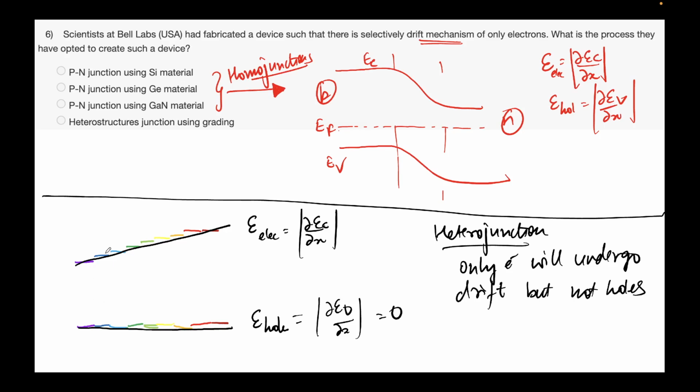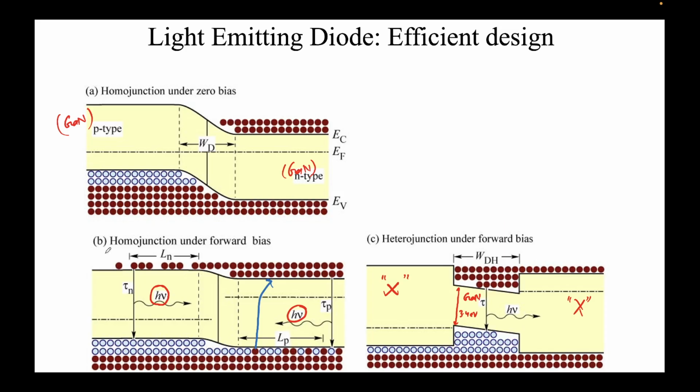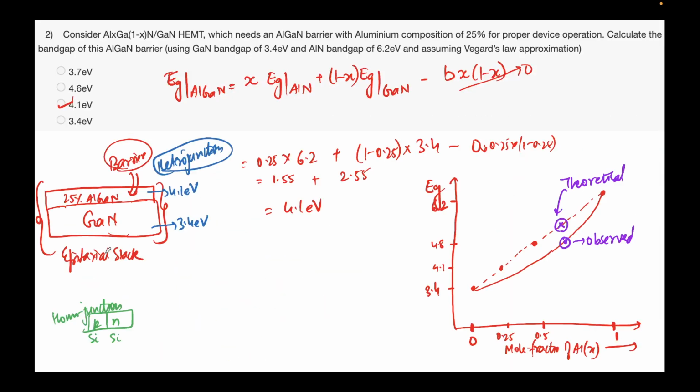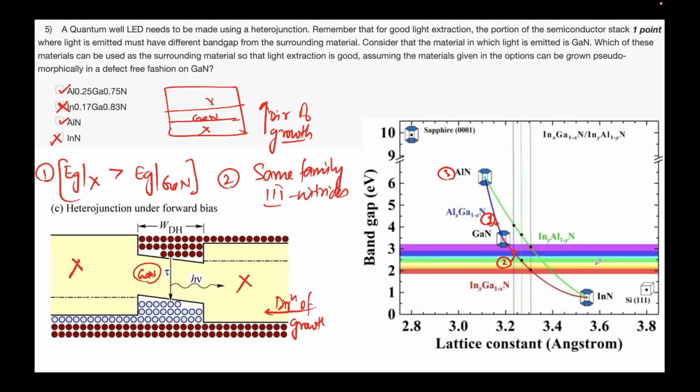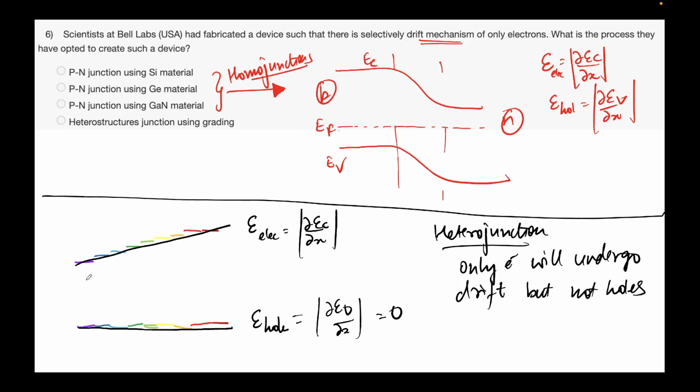First of all, again, please remember they have to be of the same family. So let's go back to the diagram. This one, yeah. Which family do I choose? Gallium arsenide and aluminum arsenide. You see their band gap is more or less similar, so they can be grown on top of each other. The energy of gallium arsenide is smaller, aluminum arsenide is larger. So this edge is perfect gallium arsenide, and on this side we have aluminum arsenide.